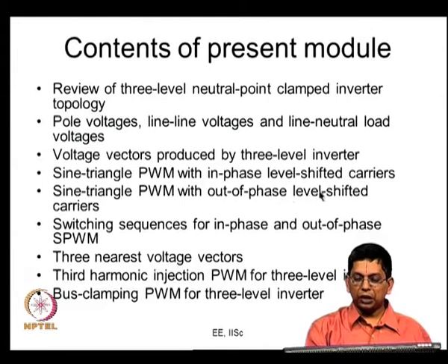Now, what we are trying to do is, in the same leg only, for the same sinusoidal signal, you can have level shifted carriers. There is no real advantage by doing this in many cases. You can actually use out of phase, but as we just discussed in the last lecture, in phase level shifted carriers are better than many other possibilities. So, they give you low harmonic distortion.